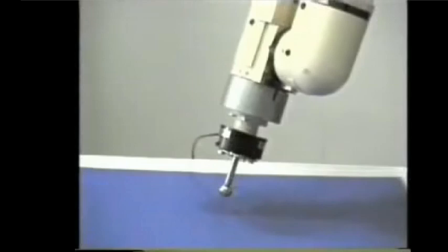So if you specify a desired force, for instance, in the direction of the carton box, on the vertical direction, and you're not measuring any forces, the force controller will generate a command of motion. And this command will be treated as a position reference by the inner position controller, and so you will try to reach this situation.